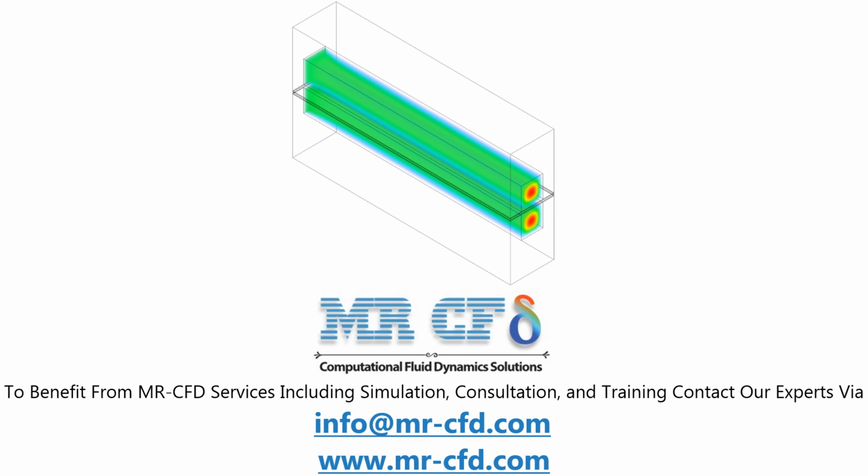Flow collectors are made of solid material with thermal energy sources and electrical potential. The flow channels carry a mixture of gaseous species including oxygen, hydrogen and water. The catalytic part consists of a porous medium with a porosity coefficient of 0.5 and contains mass sources: thermal energy, electrical potential, proton potential, saturated water, hydrogen, oxygen, and water.